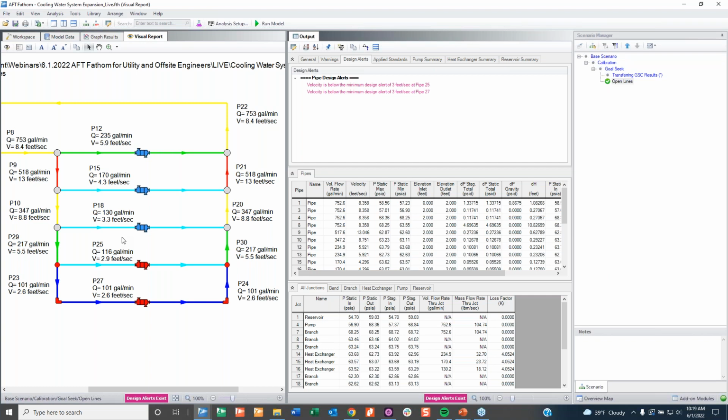What if we increase the local resistance in these 2 top lines right here, where these are smaller pipes? So if they're smaller pipes, well, then more flow is going to be distributed down lower because there's a little too much in this top line. And then the third one is, what if we were able to insert some throttling valves in these 2 lines, or orifices would be an equivalent.